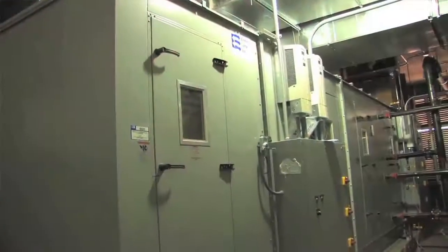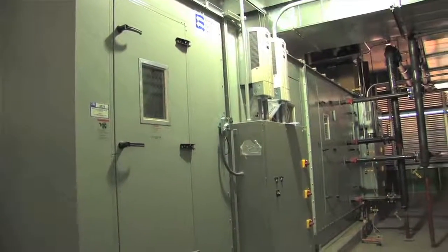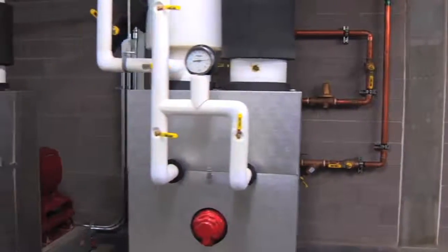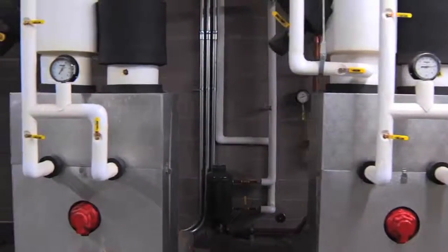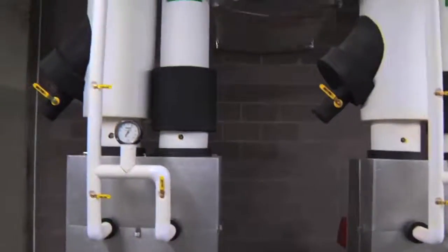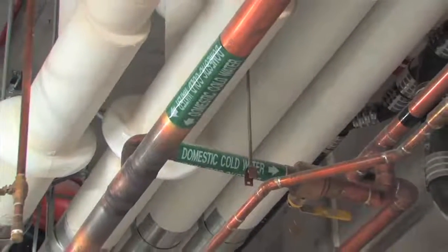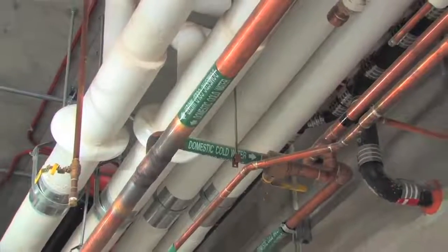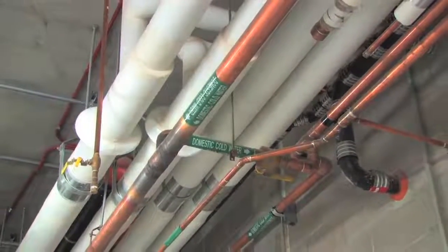The scopes that were commissioned on this project were the building envelope, mechanical systems, which include the heating hot water system, boilers, heating pumps, and recirculation pumps and whatnot. Also the chilled water system, which includes heat exchangers and, again, distribution pumps. We also did the domestic water system and lab plumbing systems, verifying piping, verifying equipment, water booster pump and whatnot.